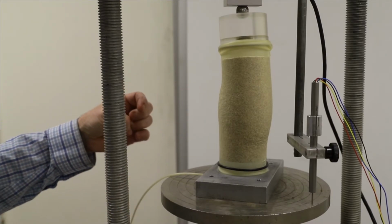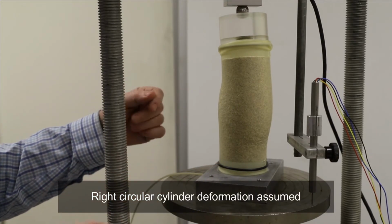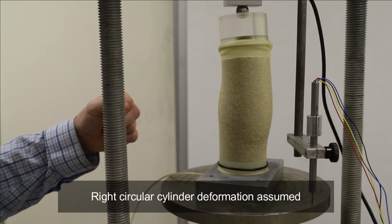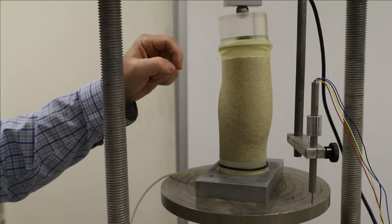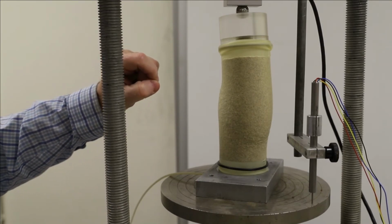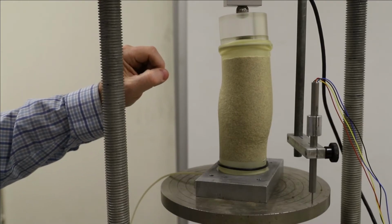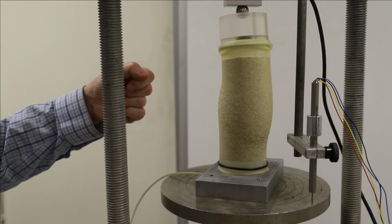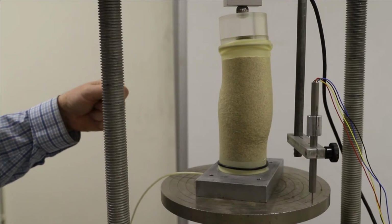When we do calculate a new area for the specimen, we're actually going to be assuming that it's deforming as a right circular cylinder, but you can see from this test that that becomes a worse and worse assumption at very large strains. You can also see perhaps that the top cap is tipping somewhat, so we're getting some moments in there apparently, or tendency for moments. So we're going to call the end of this test pretty soon, and we'll take this apart and rebuild and see how a dense sample behaves differently than this.